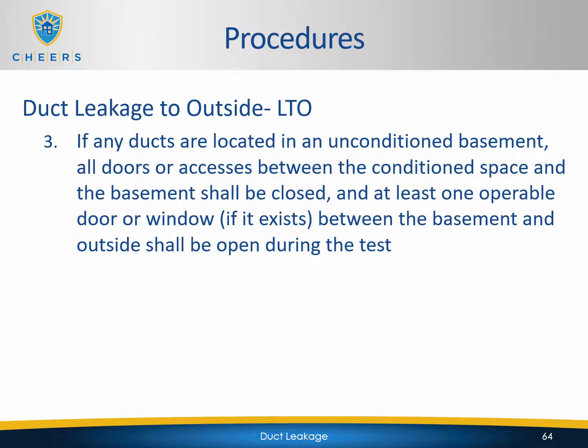If any ducts are located in an unconditioned basement, all doors or accesses between the conditioned space and the basement shall be closed, and at least one operable door or window, if it exists, between the basement and the outside shall be open during the test.